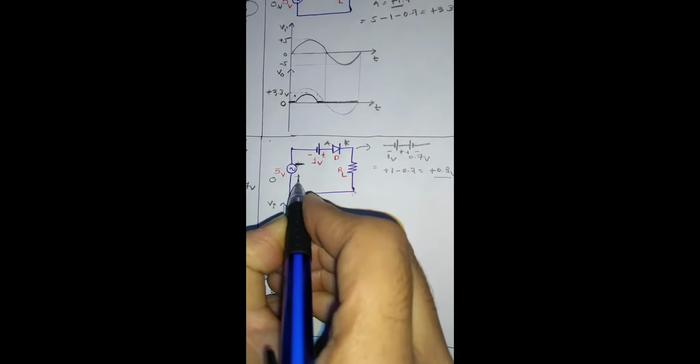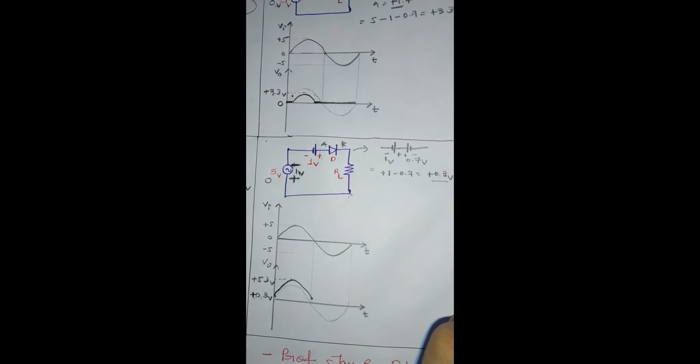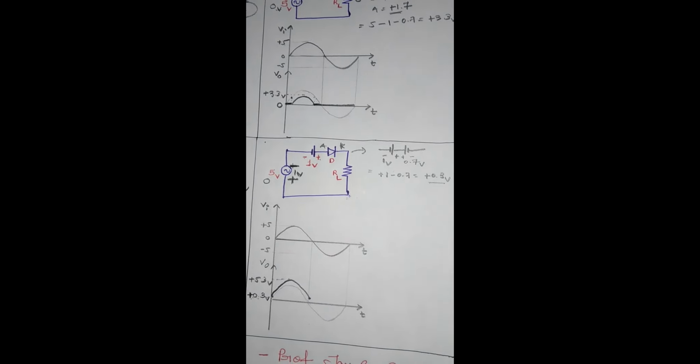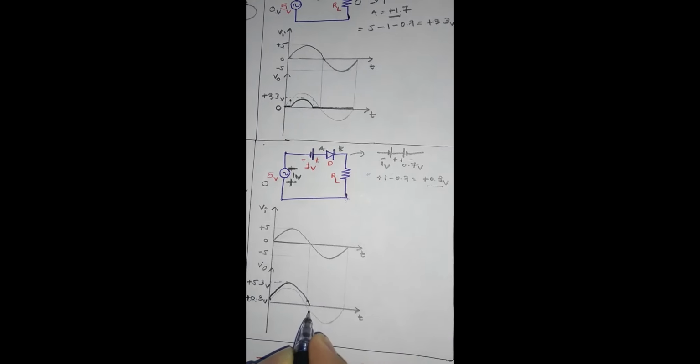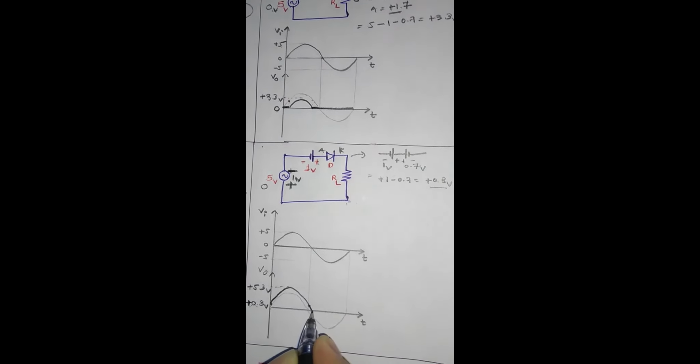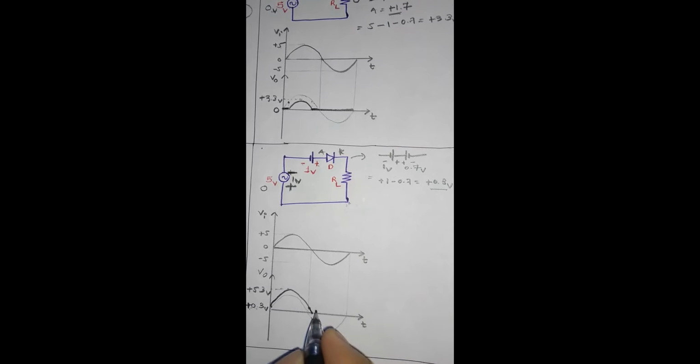So after that comes the second cycle, the negative half cycle. In the negative half cycle, consider minus plus. Initially, you have to apply 1 volt. So plus minus minus plus. So both sources cancel each other. So anode is equal to 0. So D is off. So up to this voltage D is off. So up to some input voltage of the negative cycle, your diode is off. Then when the diode is off, your output voltage reaches the 0 level.